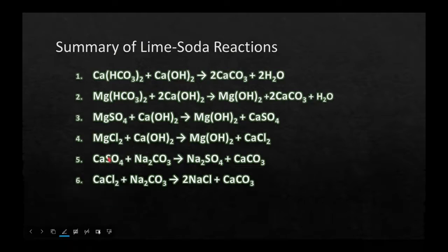Now then we've got this bicarbonate, HCO3, and bicarbonate is what we call a form of alkalinity. So alkalinity also has 2 other forms, and you guys have done a P&M alkalinity test, and you've probably done several of them.